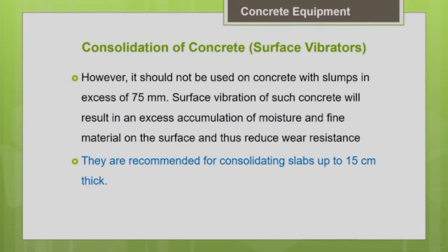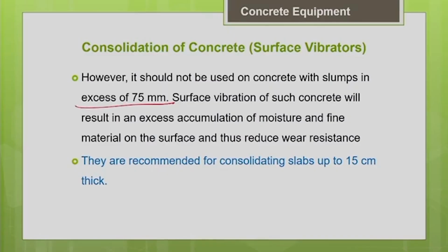One thing to be noted here is that surface vibrators should not be used for concrete with a very high workability, above 75 mm. For such highly workable concrete mixes, we are not supposed to use surface vibration, because there are more chances for segregation.